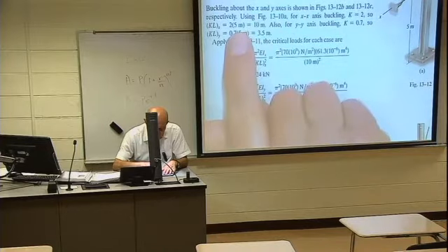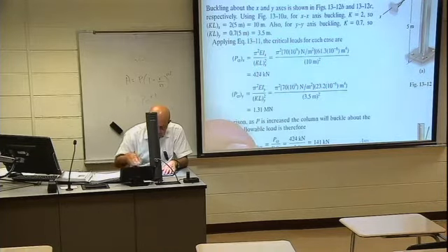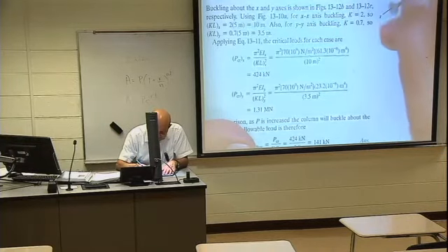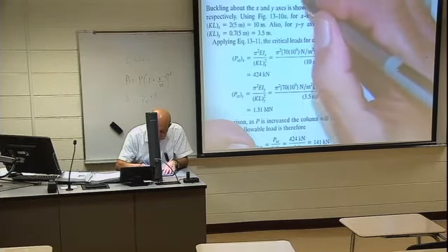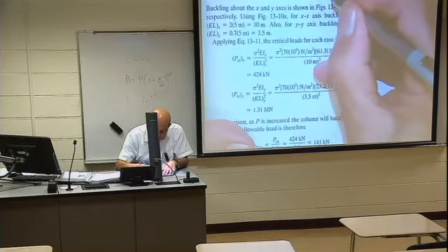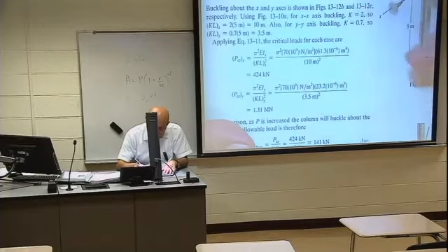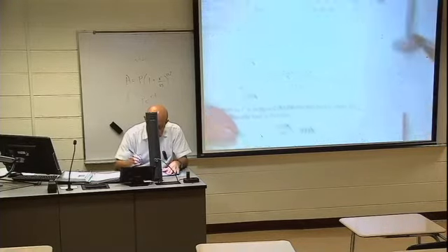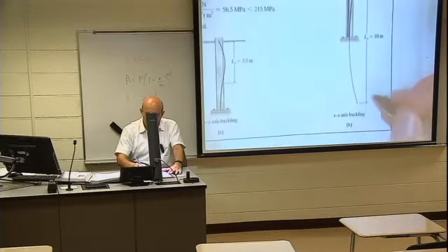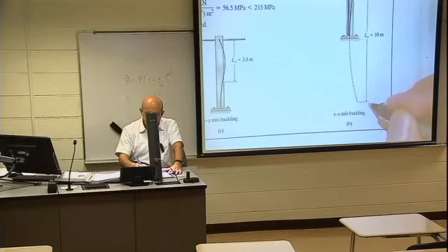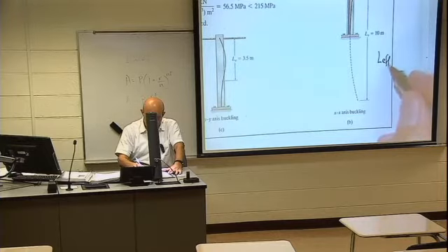Yeah, 5 meters, okay? Anyways, length equals 5 meters. So that means that effective length, because it's clamped free, equals 10 meters. Okay, L effective equals 2 times L equals 10 meters.